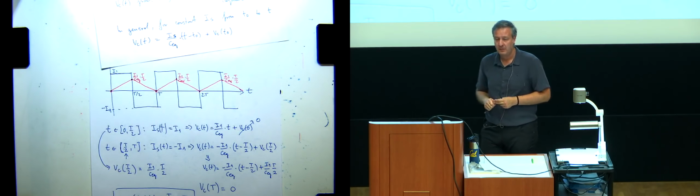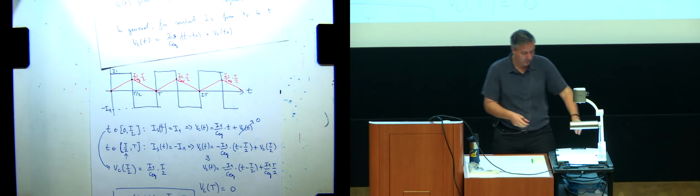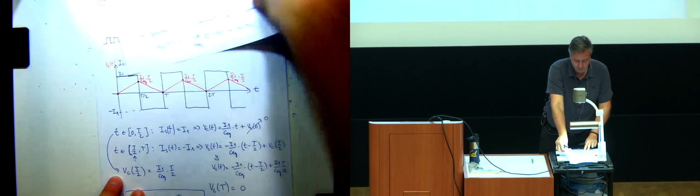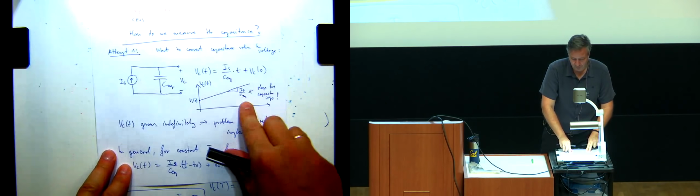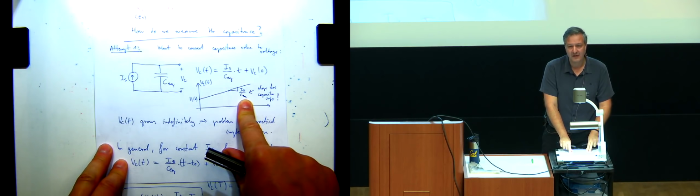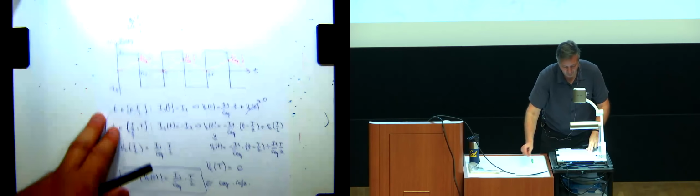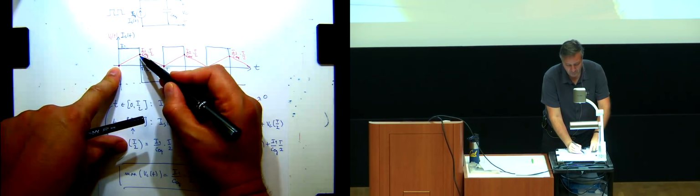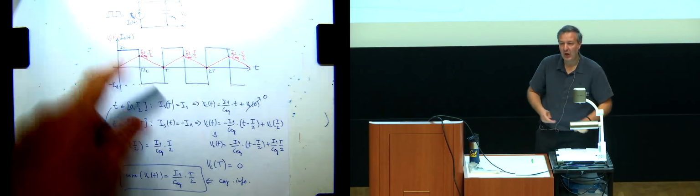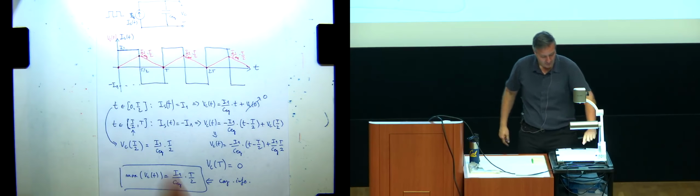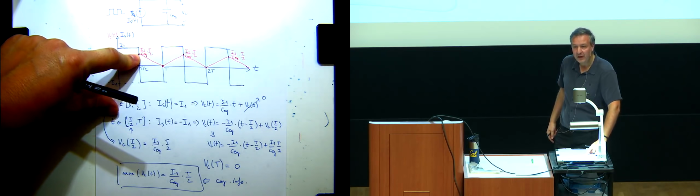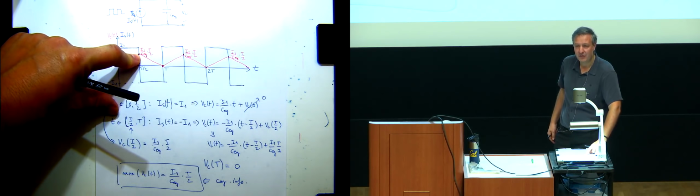Does that make sense? So previously, when we were just integrating with a constant source, our value of the capacitor was in the slope. When we applied the periodic one, now, because we've limited the time that we're integrating, the peak value of the voltage has the capacitor information.